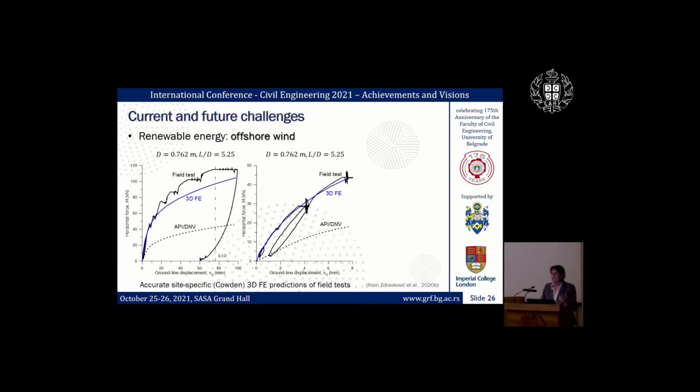And having convinced the certifying bodies and the industry who was funding all of this that we can do this from 3D FE analysis, then the real scale monopiles were analyzed, and from those it was possible then to go back to a Winkler type model, but defining not just a single soil reaction from a distributed lateral load, but 3 more soil reactions from distributed moment down the pile, a base shear force, and a base moment.